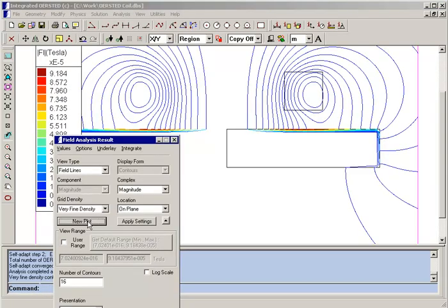we now see a combination of the effects observed in the conductive and the permeable materials. The flux is not completely expelled away from the plate like it was with the pure conductor, but neither does it penetrate as far into the plate as it did with the non-conductive steel. Rather, it enters the plate and then skims along the very surface of the plate due to the skin effect.